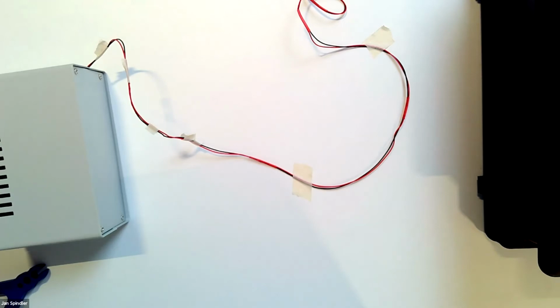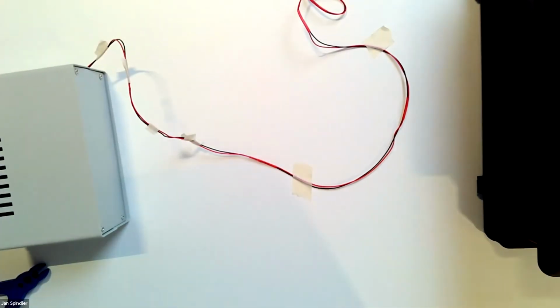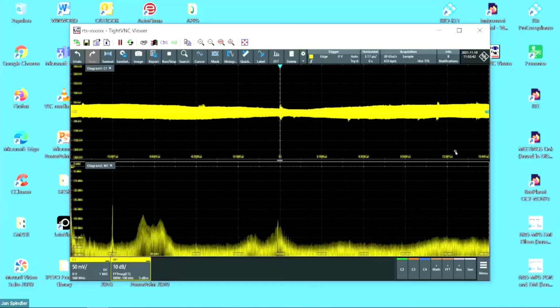Let's activate the FFT. This is the signal from the antenna. And let's put the frequency range from DC to 300 megahertz, and with a resolution value of 100 kilohertz. Okay, something like this. It's disconnected, sorry. Wait a moment. This one. Okay, this is ambient noise.